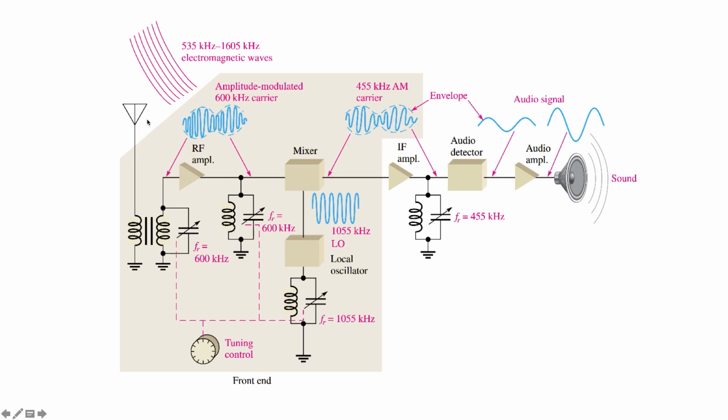While the antenna acts as some sort of filter, it still receives a large range of electromagnetic frequencies. The tank circuit filters out all the unwanted signal but keeps the 600 kHz signal. In this configuration, you have two tank circuits in series, both operating at 600 kHz. Such a dual series filter is called a second-order filter. It improves the selectivity by increasing the slope of the signal.